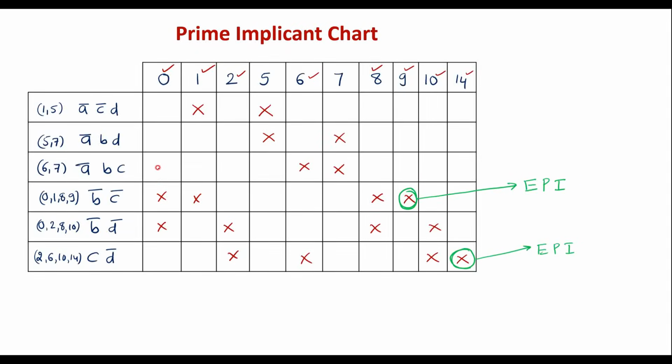So now we are supposed to consider the prime implicants which should cover 5 as well as 7. So we should consider another prime implicant along with the essential prime implicants such that it covers the remaining two min terms. If I consider 1 and 5, 1 is already covered and with this we can cover 5, but 7 is not covered.